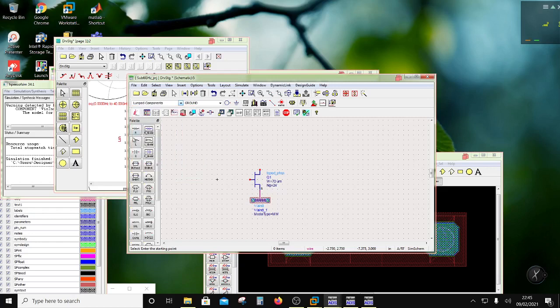So I am going to put here lumped components, and I am going to put here, let's say, 5 nanohenry with the 3 ohm resistance. Okay, so I'm going to put here 5 nanohenry with the 3 ohm resistance, right? And then I'm going to use the same thing on the other side for the gate, right? So this is done, and then I'm going to use a bypass cap, right? So let's say I'm going to use all ideal components for now, other than this via, which was important. This I'll put as, let's say, 4, and I'm going to repeat that on the other side.